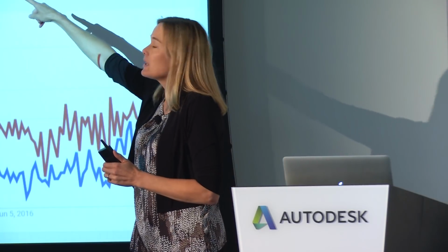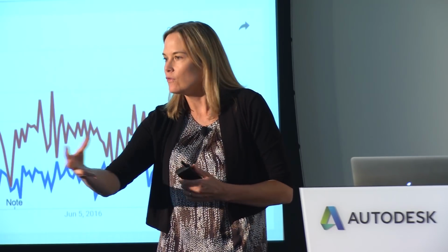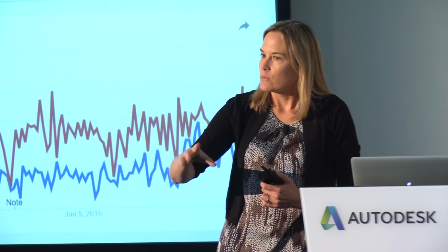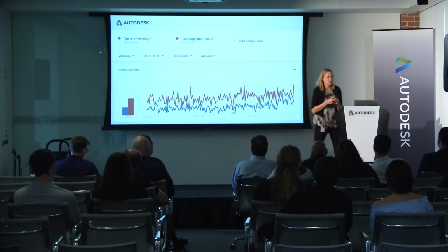So the idea that we can recruit an algorithm to optimize a form. The difference with topology optimization is I have given the system a seed, a design that I just want to lightweight. I want somehow some help to remove material. And so you would conduct simulation. The algorithm will tell you where you can remove material. But I had to create that design from my mind. With generative design, the algorithm is synthesizing the solution and returning not simply one optimal solution, but a range of solutions.